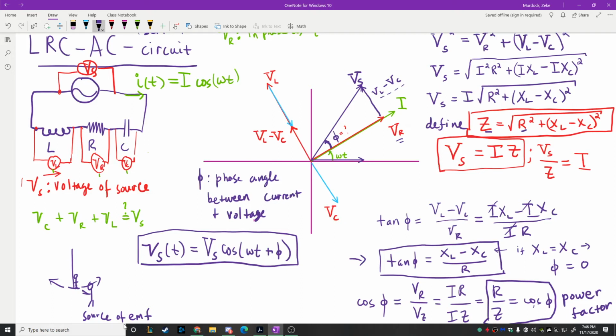And how does that show up? Well, power in Newtonian mechanics is force times velocity times the cosine of the angle between the two of them. And when they're always in phase with each other, this term is 1, and you just get power equal to force times velocity, right? So can you kind of see why we call it the power factor? If you're pushing the child to the left and the child's moving to the right, you're going to sap energy from the system. Does that make sense? The child's coming towards you and you push the child in the same direction, the child's going to slow down, right? But if you always push in the same direction as the child's moving, then you're going to get an amplification of the power in the system, right?